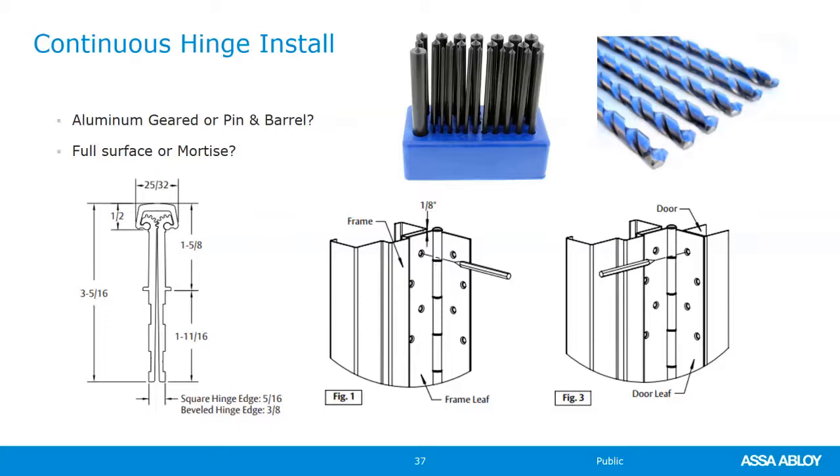It's very, very difficult if we put the hinge on the door and it's nice and straight on the door, then we try to move the door and the hinge to the frame and hold it still and get it blocked and get it shimmed and everything we need to do, and then install and mount the hinge on the frame. It's much easier to deal with the hinge as itself before we mount it to anything.